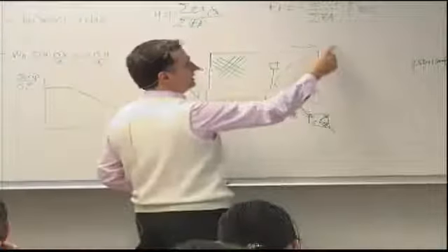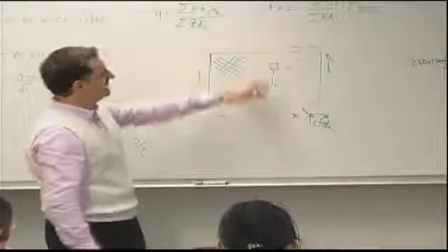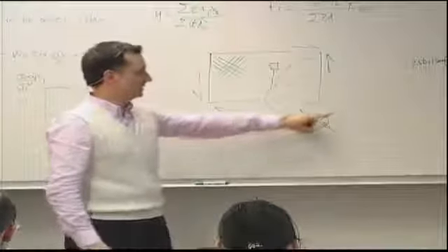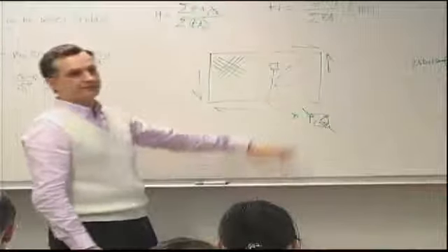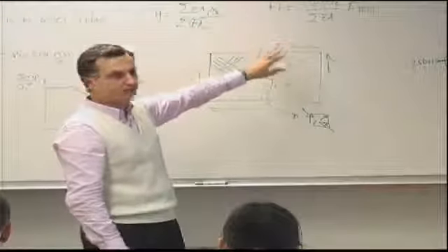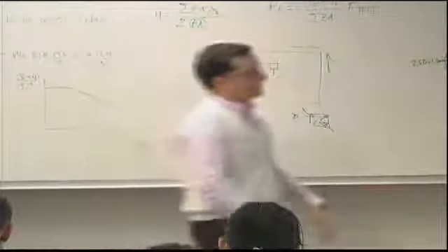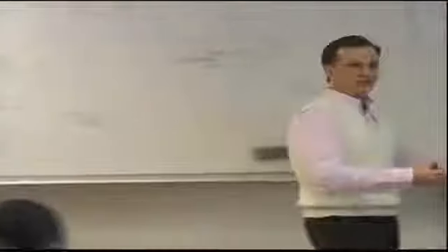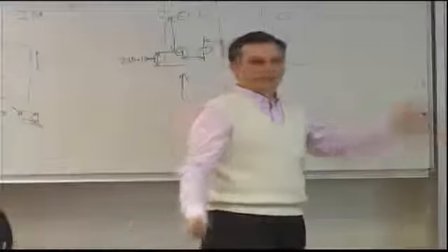So I can effectively keep increasing this until I break fibers in tension in the plus 45 degrees, and I have a good performing structure. So shear, the skins, that's why skins take shear loads. That's why we do shear flow calculations for skins, because that's what they do. It's the best thing they can do.